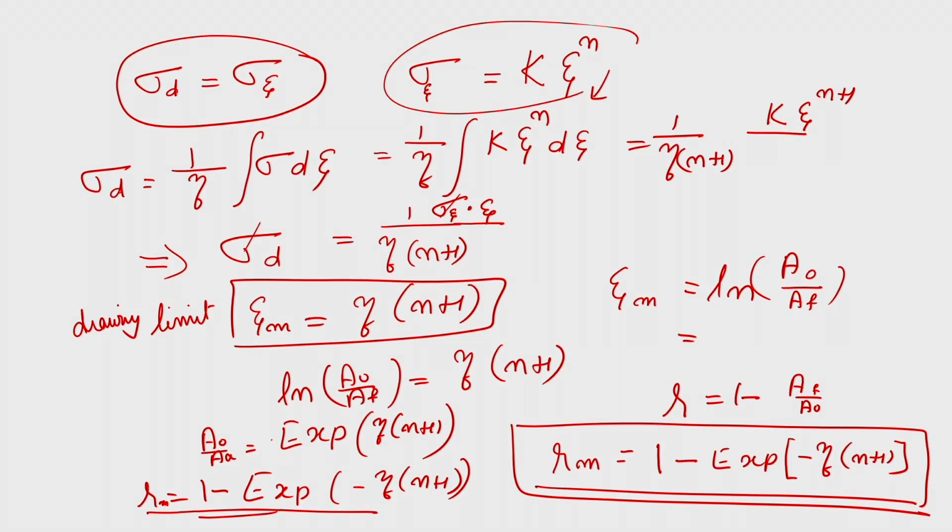So, if you want a material which is not work hardening, the best way is that you do some large amount of plastic deformation. Only thing is that ductility will be very poor, but you will get a material which is not work hardening. So, that is one way of carrying out experiments with samples which are not work hardening, or with a different work hardening rate if you wanted. These are the methods by which people do. So, when you are repeatedly doing reductions, the n will decrease almost to 0, and the allowable reduction keeps on decreasing in this case from this expression.